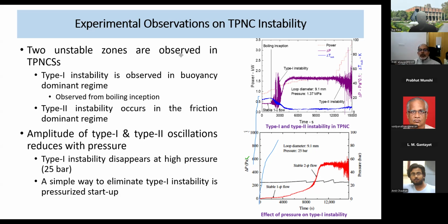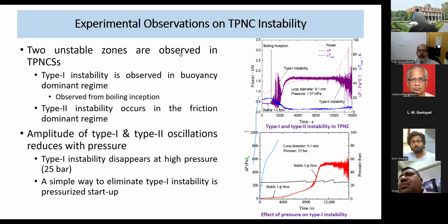But if you switch to natural circulation, this problem is avoided, because natural circulation generates a flow proportional to the power absorbed by each channel. So there is no need of a control; the phenomenon itself controls the flow.